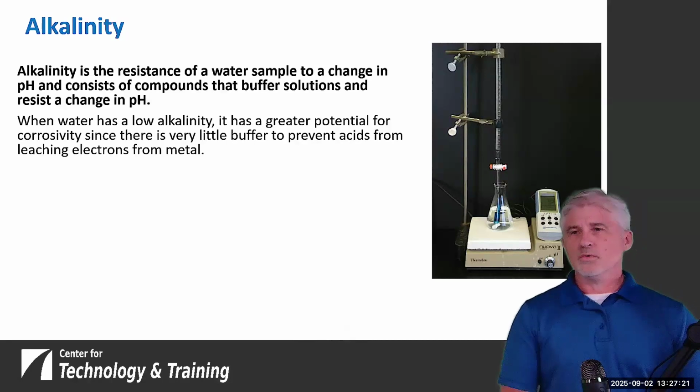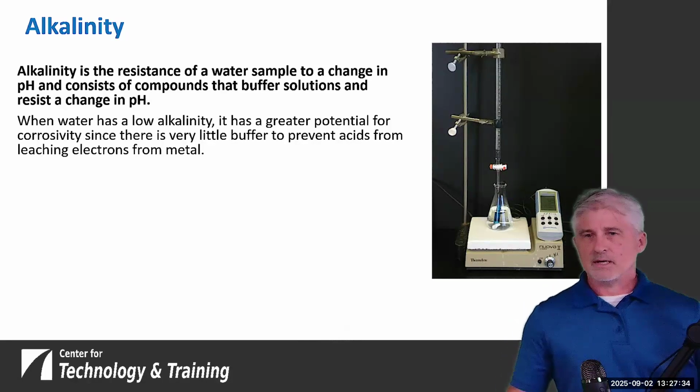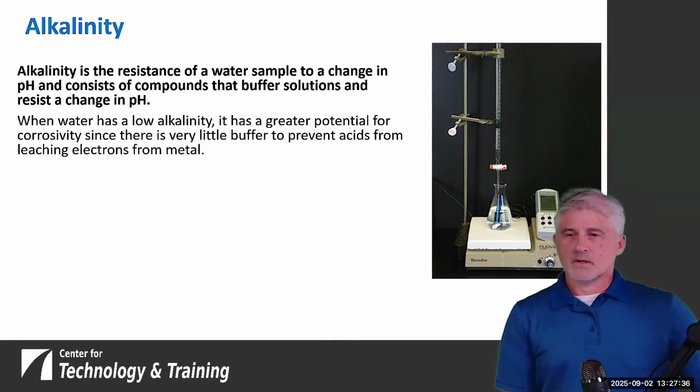If water has a low alkalinity, it's got a greater potential to be corrosive because it's lacking that buffer to prevent the acids from leaching electrons from the metals.